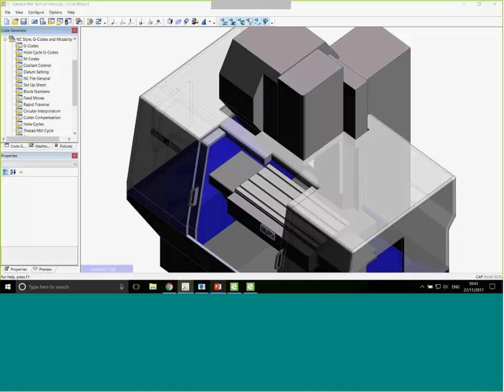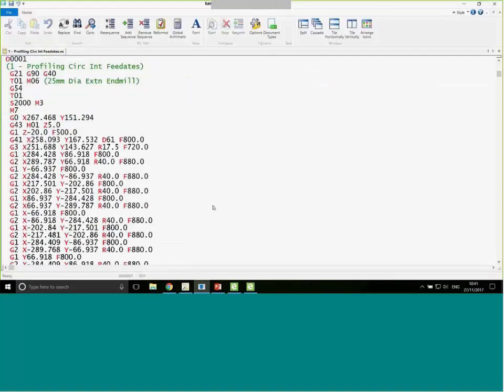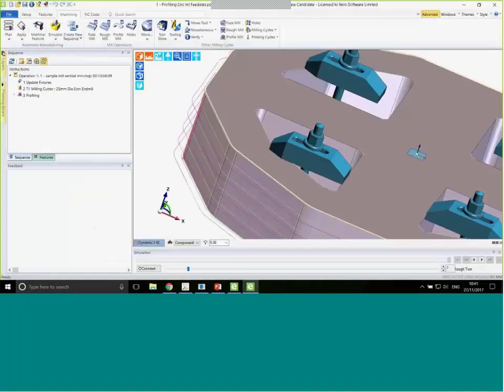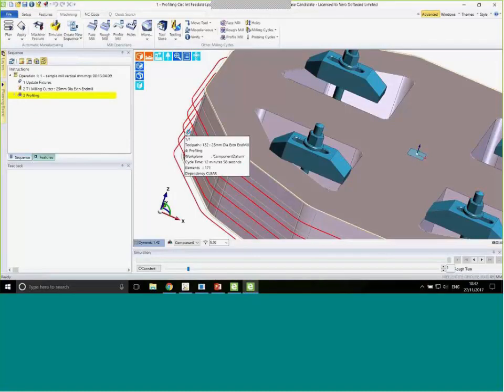And the net result of that is, if we look at the output, you'll see that when we're doing a G01, we're at 800. Where we're doing external or internal G02s, G03s, notice how wherever we do any type of circular interpolation, we're getting an adjustment. And that's exactly what we want. But the issue has been that our cycle time hasn't been perfect, and this is where the small fall down has been. This should really reflect what we see generally on the machine tool. This has always been an approximation.